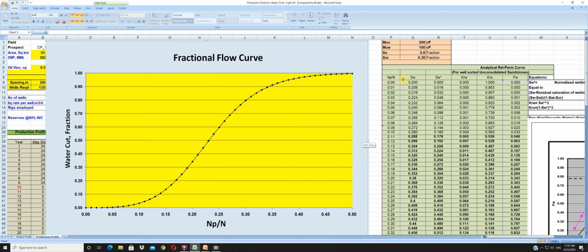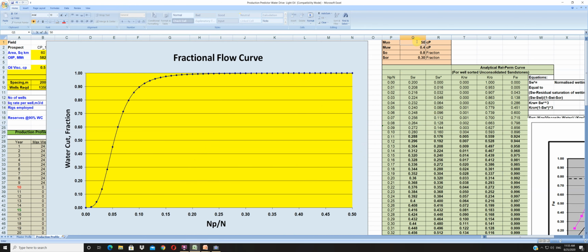So this is what 5,000, and let's go back now to the original condition of water and 500. Now if it is extra heavy oil or extremely viscous oil, well, you have a very quick water breakthrough at around 90%, less than 5% recovery. What to do? Why wait for a water flood? Well, go and inject steam or polymer.